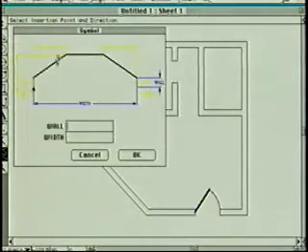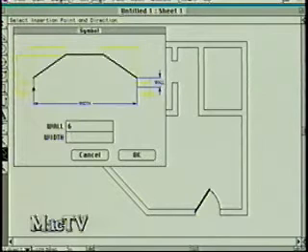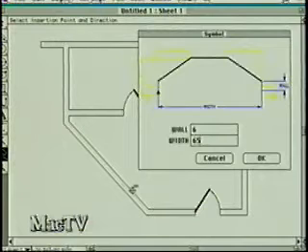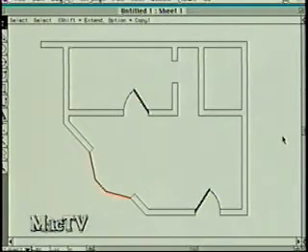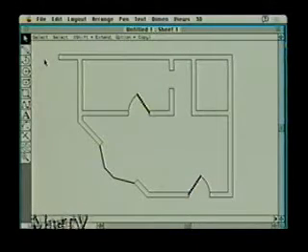So I've got a bay window here, and again, it's parametric. We've got a 6-inch wall. Let's do a 65-inch window, and let's put it on this angular wall, so I can insert here and indicate a direction by dragging and placing it, and then say OK. And it puts it right on that wall as well. Very powerful, very nice for creating very quick sketching of your architectural floor plan.